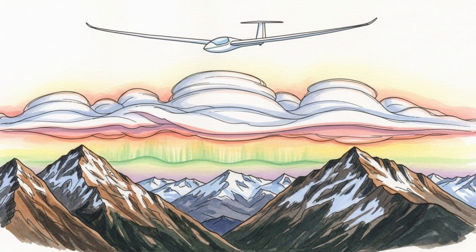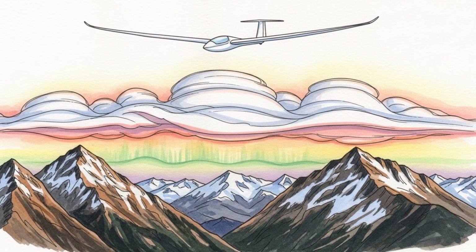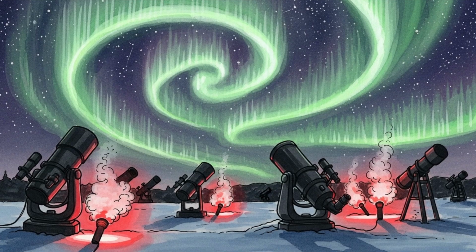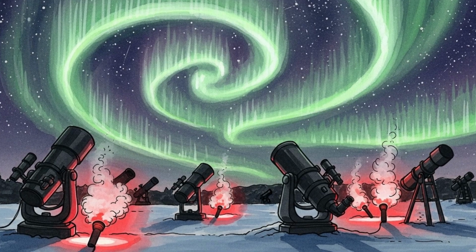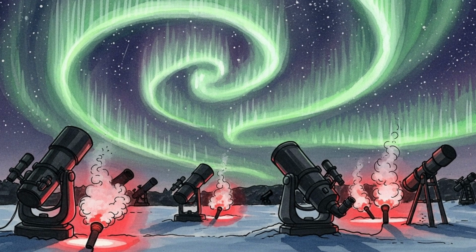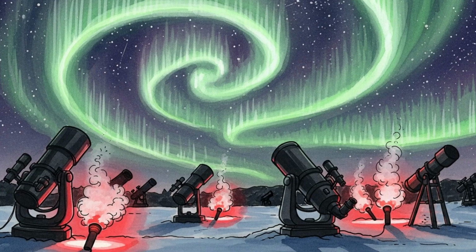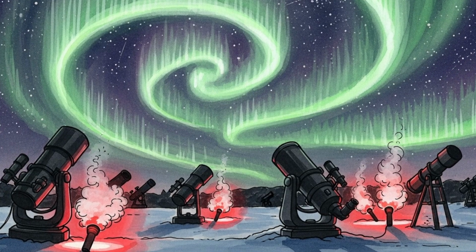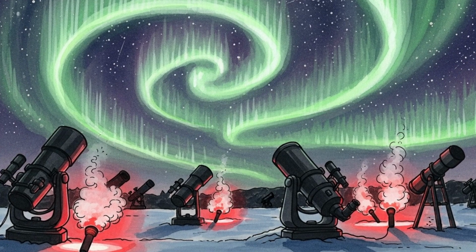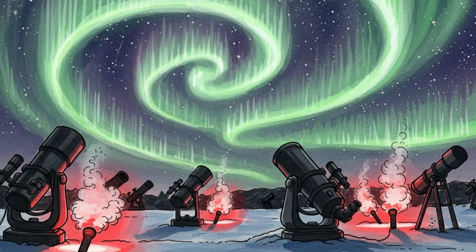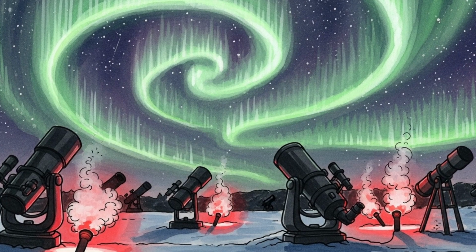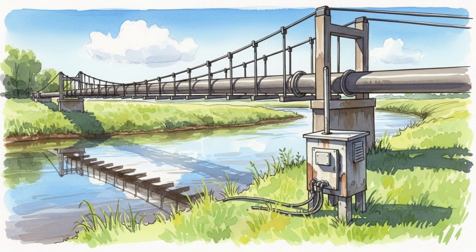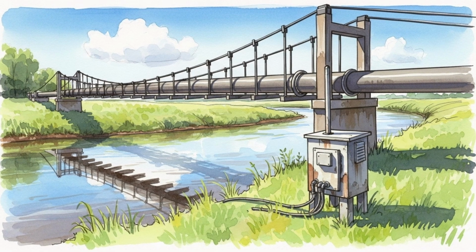Long-term improvements. Increase upstream monitoring density to reduce uncertainty in arrival time and magnetic orientation. Add ground magnetometers with higher sampling rates in regions that show the largest induced fields. Improve conductivity maps used for electric field estimation. Upgrade transformer thermal margins and neutral monitoring in key substations.